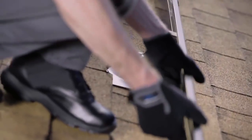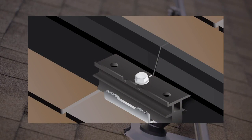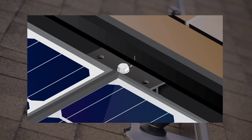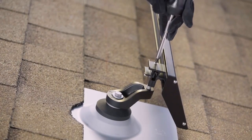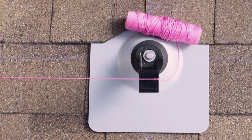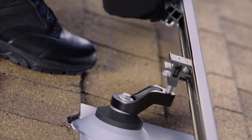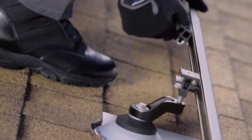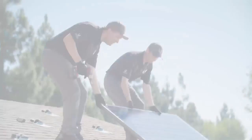Hook the trim covers onto the mounting assemblies. Then insert panel connectors at trim cover gaps as well as alignment marks on multi-panel trim covers. Finally, secure the trim kit by fastening the trim lock to the mounting assembly. To review, install mount assemblies at equal height across the bottom row, then add trim kits and panel connectors to begin installing panels.